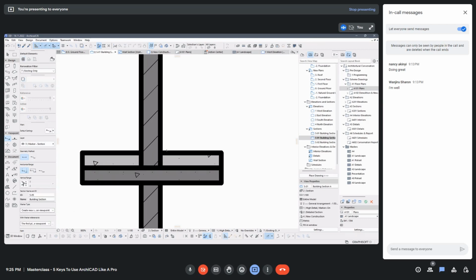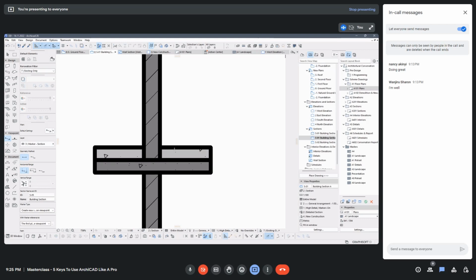So you see now how this has worked is that now masonry is stronger than blinding. You wouldn't want your masonry wall being supported by blinding. So that's why we have masonry being of a higher priority than blinding. And we can continue copying this and seeing what happens.